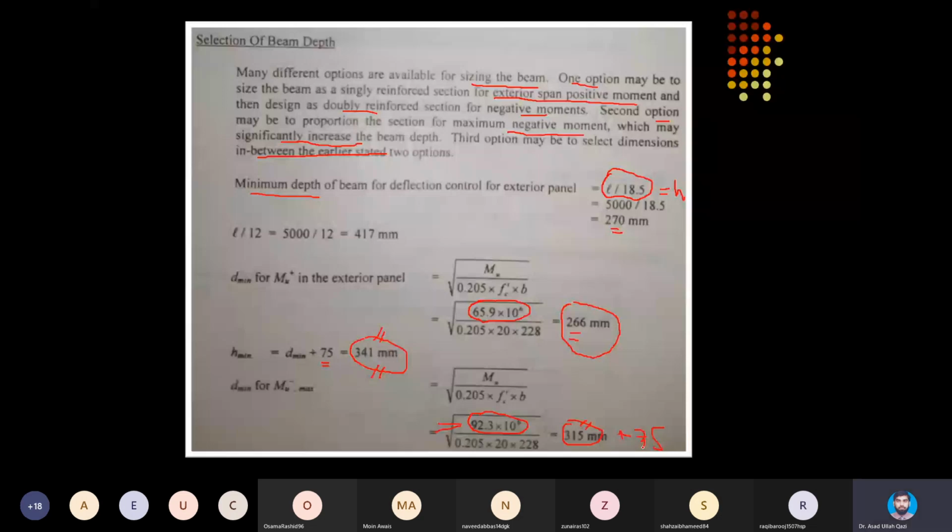So interestingly, it is quite possible that even in monolithic construction, although it seems that T-beam sections are present, nowhere you get the T-beam design applied, because over the supports they are already rectangular because flange is in tension.